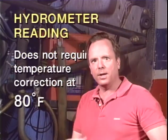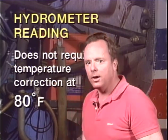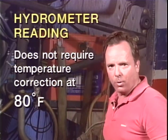And that's generally true because anywhere between 70 and 90 degrees Fahrenheit, you do not have to correct the hydrometer reading for temperature. So 80 degrees Fahrenheit is a good temperature.